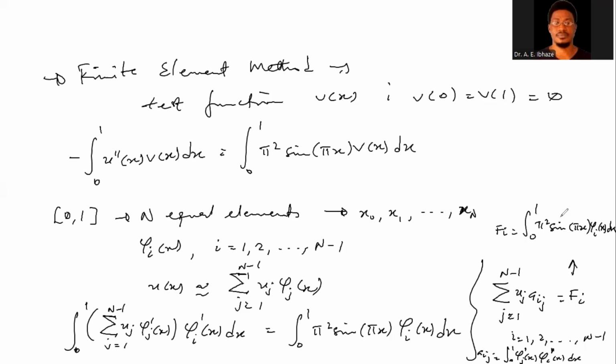So we want to assemble this on a uniform mesh. So if we assume, say, n being the same as 4, just like we already described previously using the finite difference method, then for linear elements on the uniform mesh, we'll find that the local stiffness matrix on the interval of length, say h, step size h, is given as k sub e being the same as 1 over h, for n being the same as 4, times the matrix 1, minus 1, minus 1, 1.